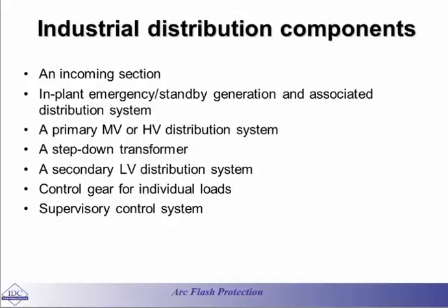So what happens is that you will connect your distribution panels at the LV side to the transformer. So let's assume the incoming is 11 kV. That 11 kV will then convert into 415 volts. So you would require to have a 415 volts panel with its bus bar, and there will be some outgoing feeders. Of course, you need to have control, SCADA, protection, or something like that, PLC or something.